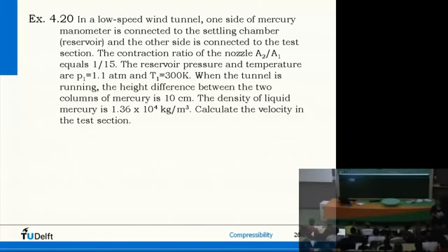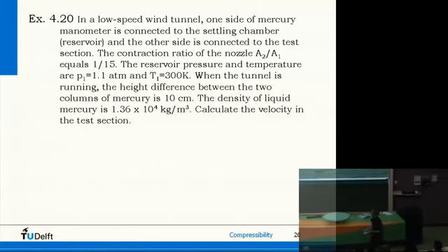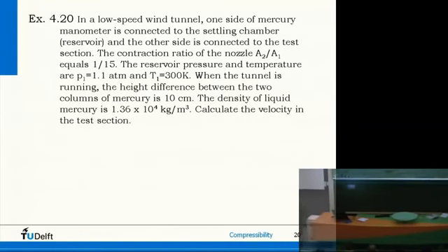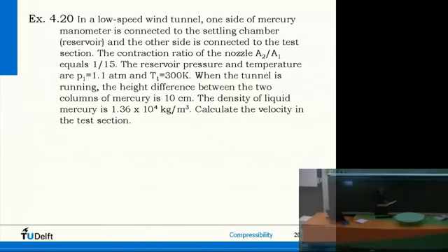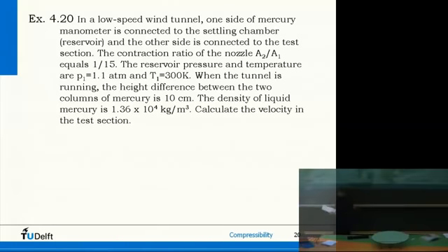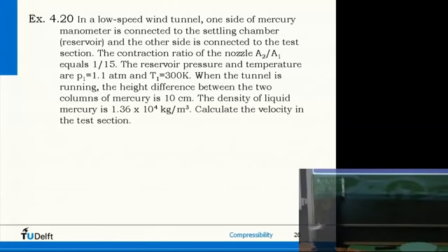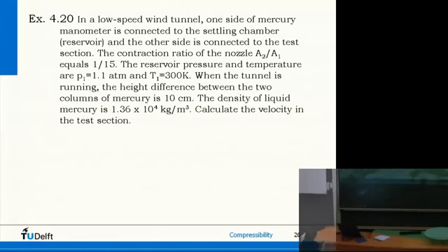I put the manometer on, right? And it's P1 minus P2, with a height. How did I know which one was the low pressure and which one was the high pressure? Because I think I said P1 minus P2, or did I say P2 minus P1? P1 minus P2. So here was rho gh. Could I have said P2 minus P1? No. Because you have to realize which one is the lowest pressure: the one with incompressible flow, the one with the largest area, right? So I use this. So A2 over A1 is 1 over 15.